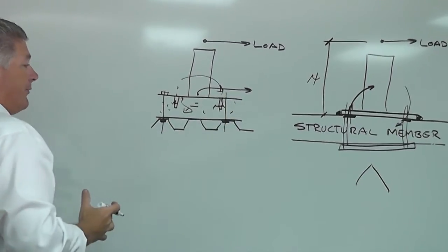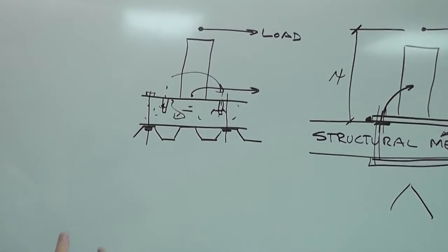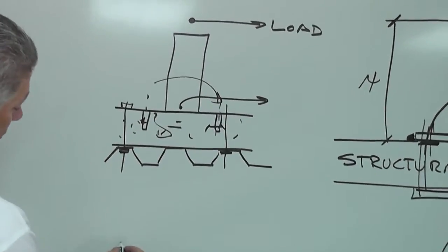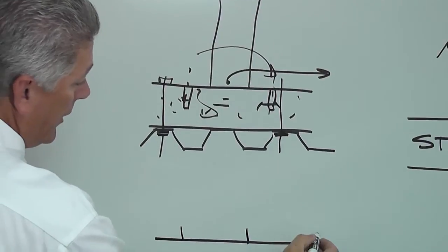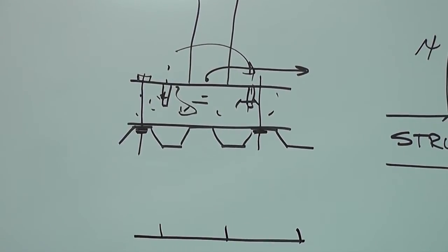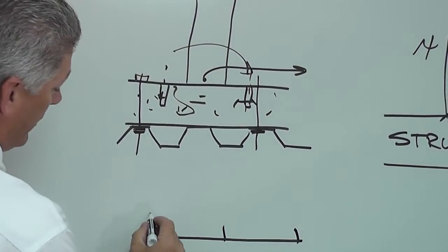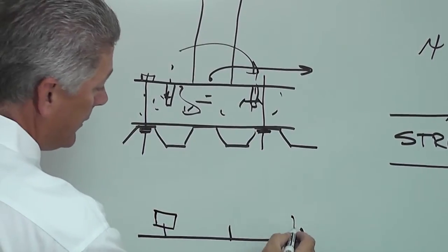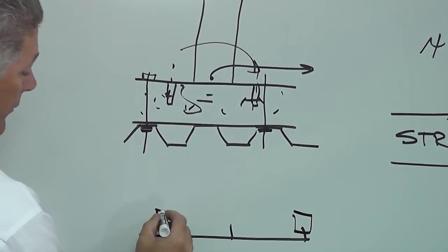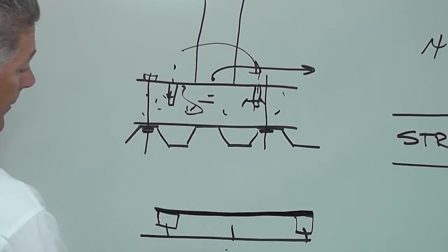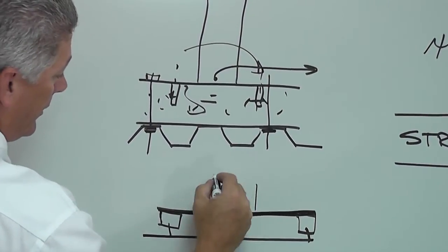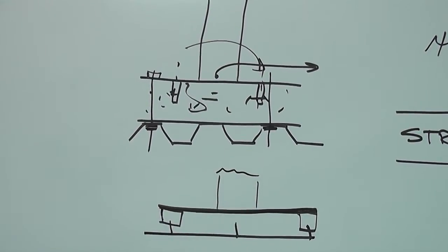We also have specific designs where the tip-over technology is used on a standing seam roof. A typical standing seam roof is going to have ribs usually every 12 inches. Our base plate would have a mounting block that attaches to every other rib. The base plate mounts between the 2 of them, and then this would be the tip-over post mounted there.